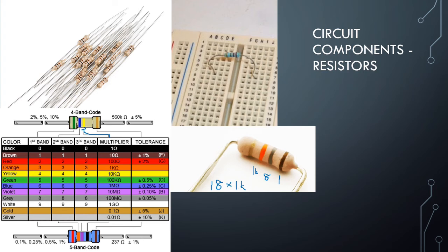If you've purchased the kit and you're working at home, as I said, I will try to include the colors for you, but you can always refer back to this chart and figure out what band color corresponds to the value. And when in doubt too, you can also Google it. I have no doubt that if we Googled the resistor band code for an 1800 ohm resistor, you would find this picture here that we just walked through. So you certainly have a lot of resources available to tell the difference between the resistors.